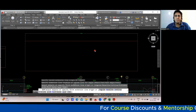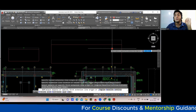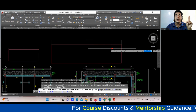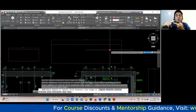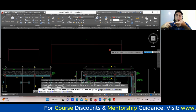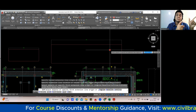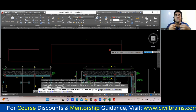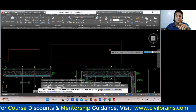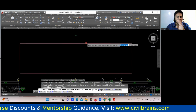So there is not much complication in the rough foundation BBS. Only the lapping portion you need to understand. While doing the execution, you need to understand about the alternate lapping. One lapping if you do here, second should come somewhere there, which when you do the execution, the site engineer should take care of. As a quantity estimator, you just have to find the cutting length, which is same for all the bars. Okay, simple, no? Yeah. So I think I've explained this concept of the rough foundation.